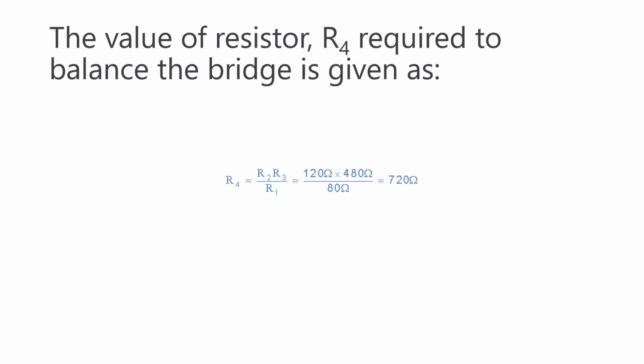In the bridge circuit, when no current flows through the null detector, which is generally a galvanometer, the bridge is said to be balanced. The relationship between the component values of the four arms of the bridge at the balancing is called bridge balancing, and the equation is the balancing equation. This equation gives us the value of the unknown component.